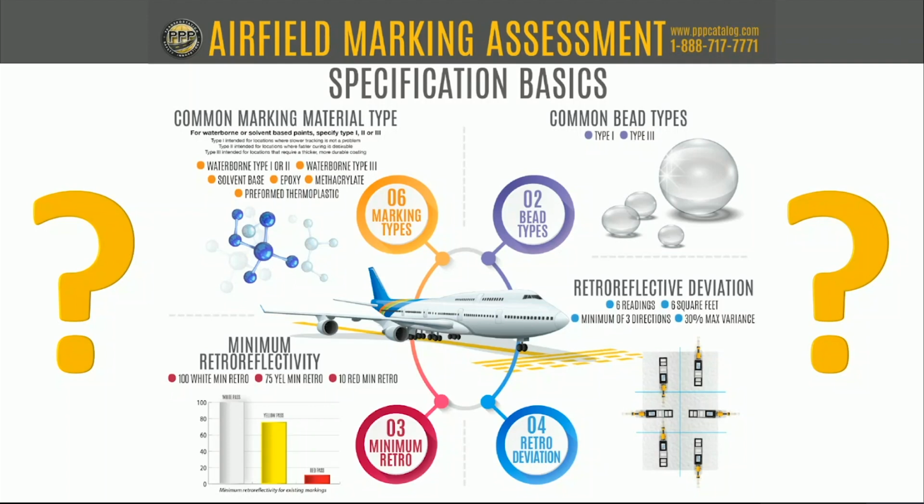So in my estimation, especially with a small handheld reflectometer, to meet the ASTM standard testing, you need to measure in both of those directions of travel. For mobile assessments, those are the ones that we use the Road Vista LLG7A. We typically measure in the primary direction of travel. It's not as important to get data from both directions.